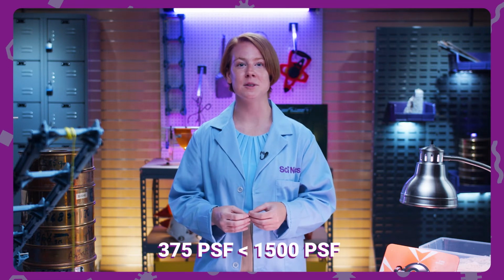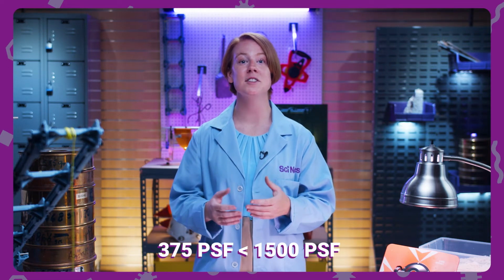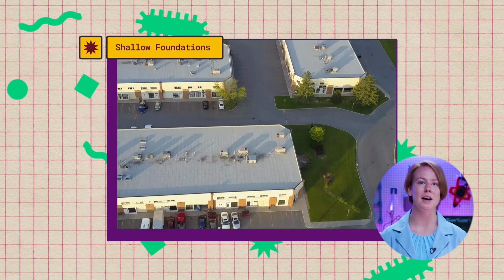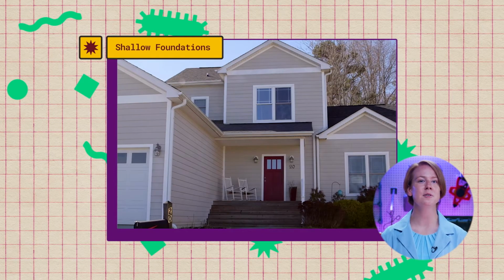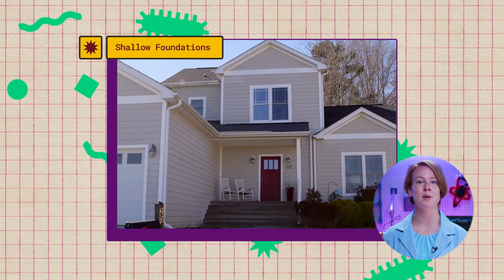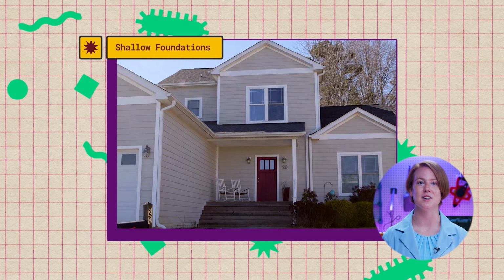The pressure that the soil experiences is significantly reduced when a footer is added, which is important for shallow foundations. Shallow foundations are only practical for low-rise commercial or residential buildings that are generally lower in weight and can be supported by the compacted soil that it sits on.